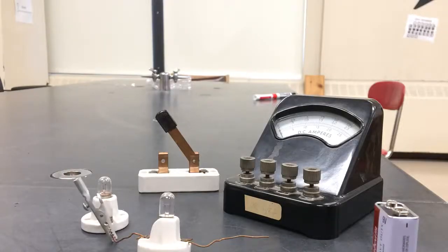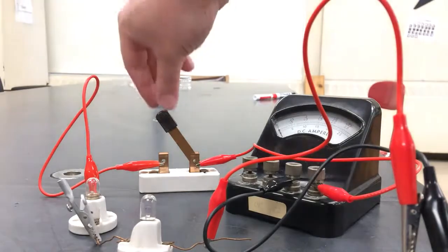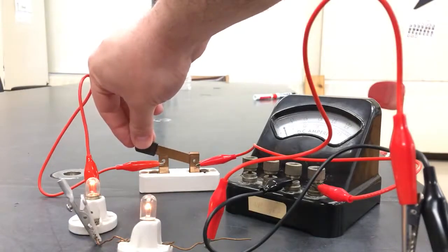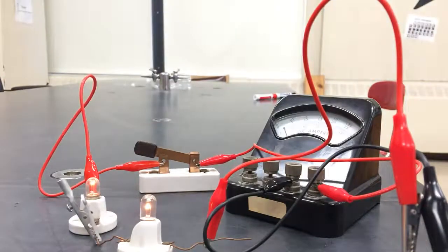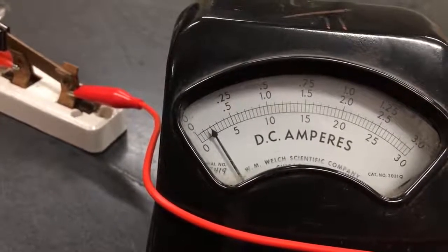So we're going to hook up the ammeter, and it's not very hard to do. We just have to put it in what's called series with the rest of the circuit. Series is pretty easy to understand. It means that as we take our journey from the negative side of the battery back to the positive, we'll pass through each element one at a time, one after another. Now obviously nothing's happening because the switch is open, but let's close it and observe. So the bulbs light up and the needle on the ammeter moves. And this meter is currently telling us that we have 0.1 amps, 0.1 coulombs per second.